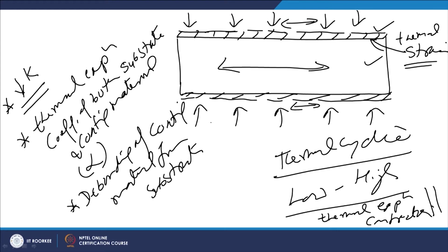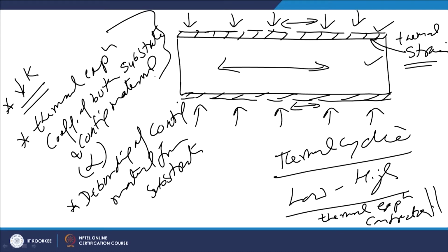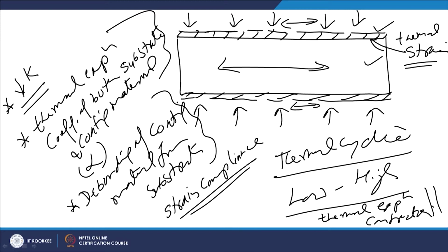So, the purpose of applying the thermal barrier coating onto the substrate will be defeated, and therefore, it is important that apart from the lower thermal conductivity, the thermal barrier coating material should have a thermal expansion coefficient close to that of the substrate material. This condition is termed strain compliance with regard to the coating material properties.